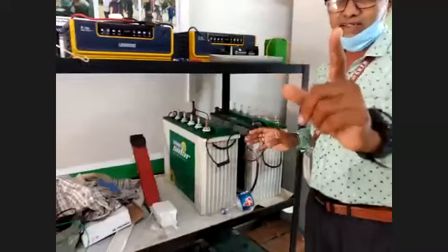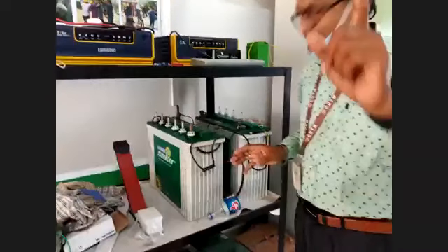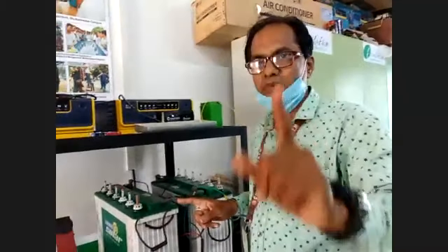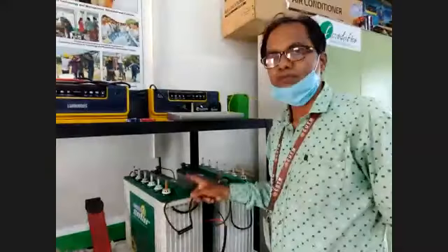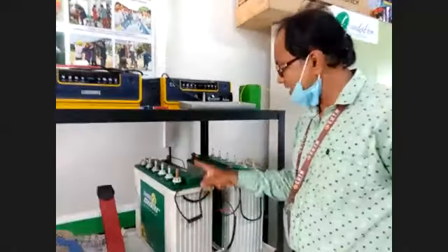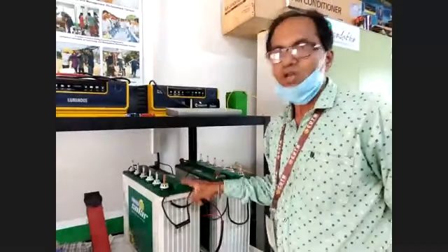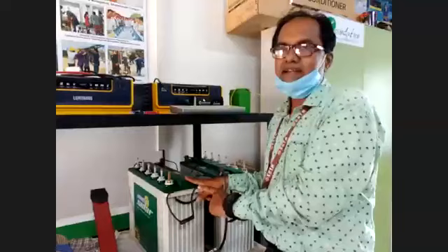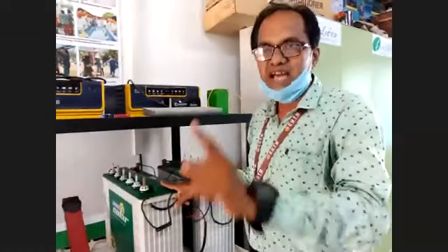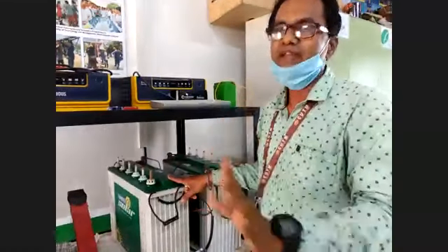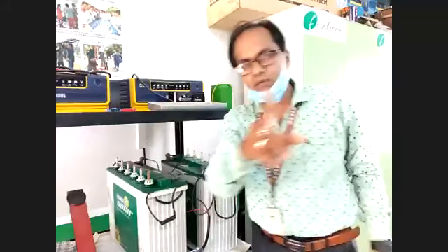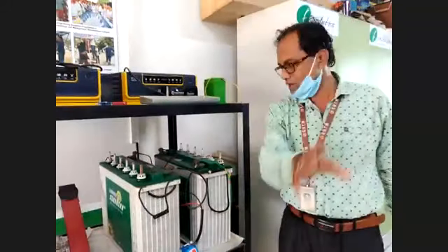But one important thing is the current factor. As you know, the fast charging of the battery actually depends upon the ampere hour of the battery. As this battery is 150 ampere hour, 1/10 of this current will be able to charge the battery fully in the shortest time. So a minimum of 15 ampere current is required to charge the battery.